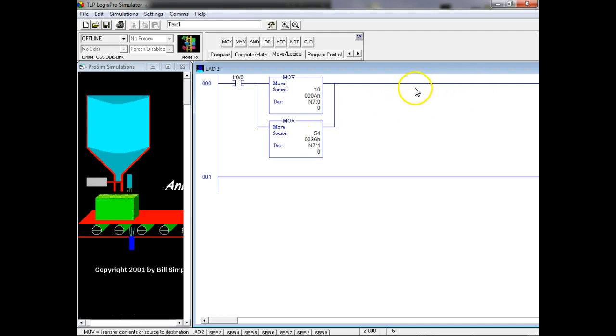Then I could come down here and we could use a switch, or we could do it automatically. Some output instructions don't necessarily have to have a control device. You got to have an output instruction on every rung. Everybody understand that? Every rung. Do you have to have an input instruction on every rung? No. If you want an instruction to be executed immediately every time it's scanned, you just don't put an input, right? It'd be an unconditional rung. So let's do it that way first.